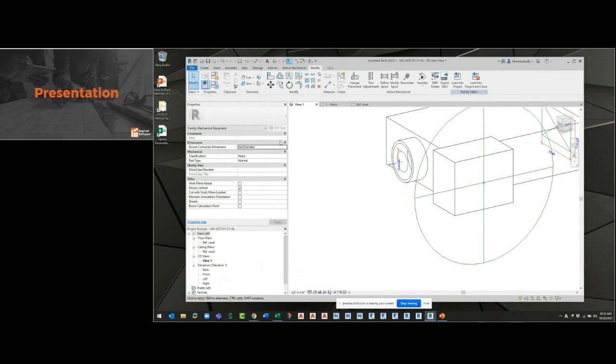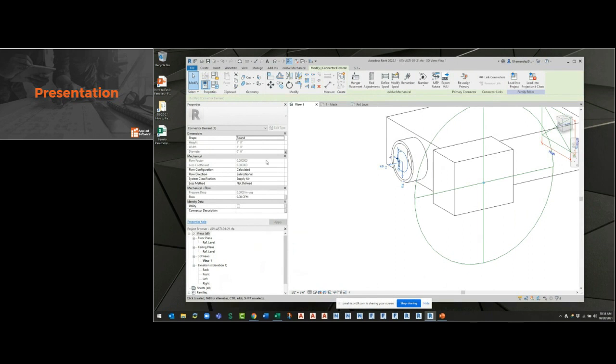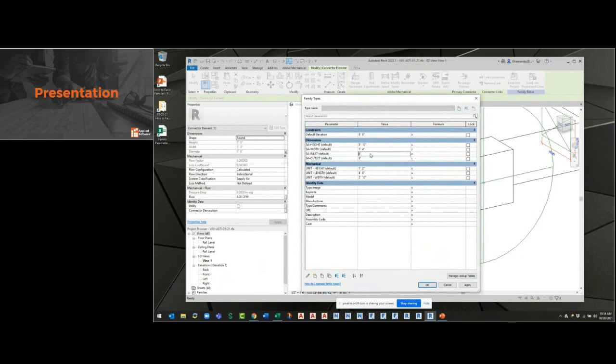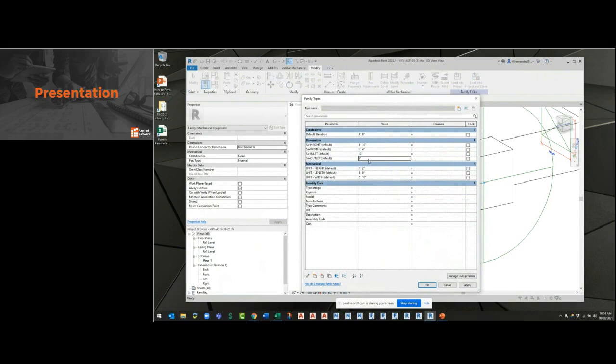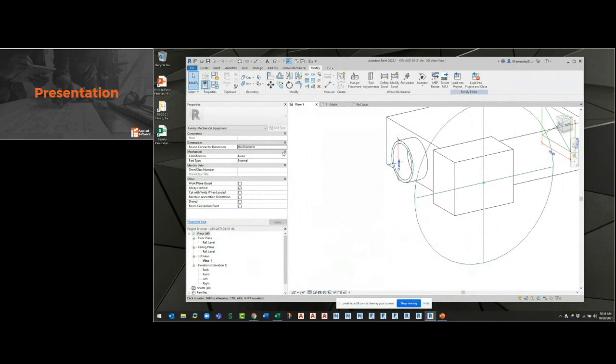And then I can say that I want to be using radius or diameter, either way. Let's see here. So it's a diameter, inlet is 6. So let's say, oops, not 1 inch. This is the difference between a duct size and a length. The length's going to give you feet and inches, but if you're only using inches for that dimension, you can use the HVAC duct size and it'll give you just inches like this. So if I did something like that, there we go, right? So it actually should be using radius. So we'll come back to that in a bit.